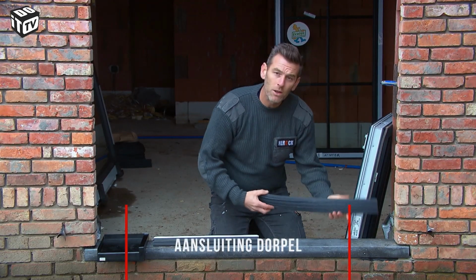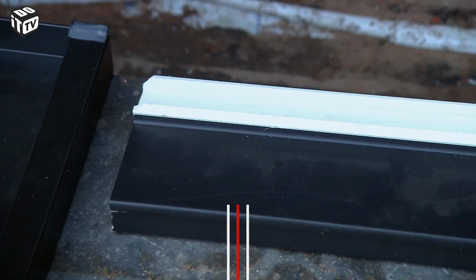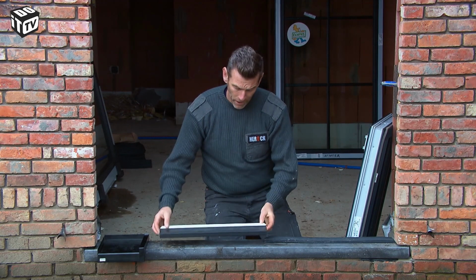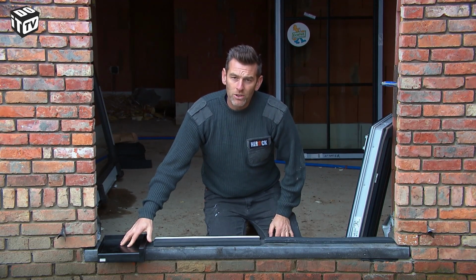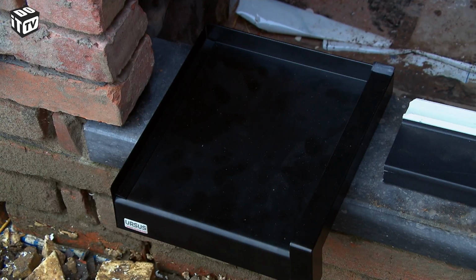If you have a new building, we'll place the window frame on EPDM rubber. If you have a renovation, we install a threshold to even out height differences between the indoor and outdoor sill. If you have a house you want to plaster with crepe and wrap with extra insulation, we have an aluminum threshold.